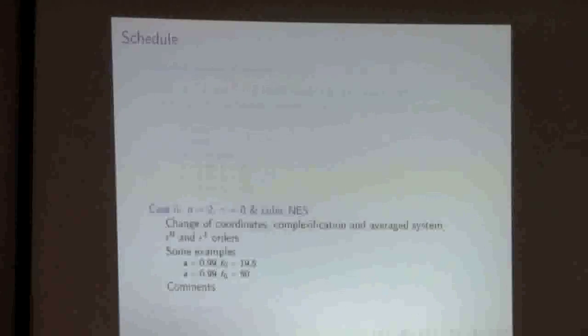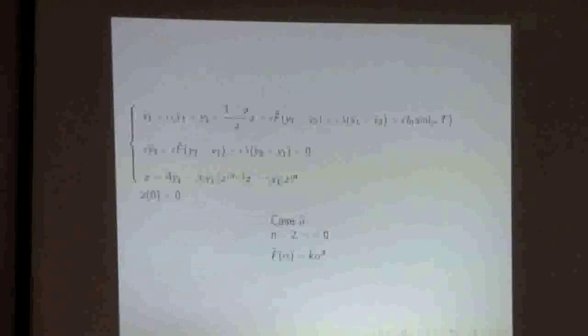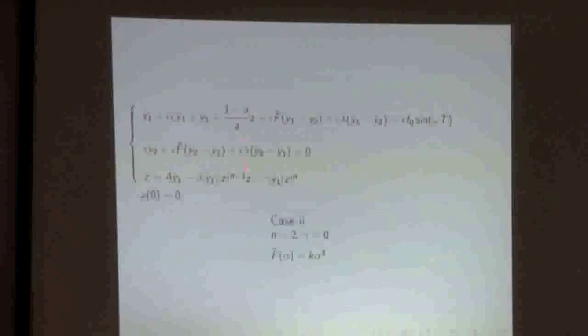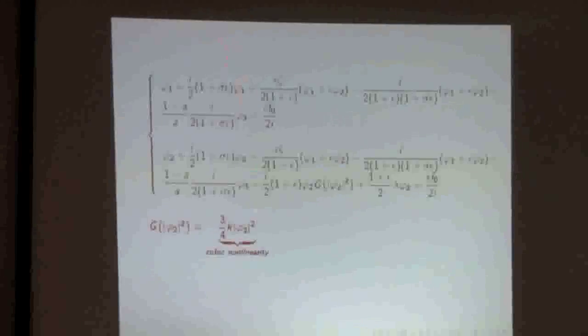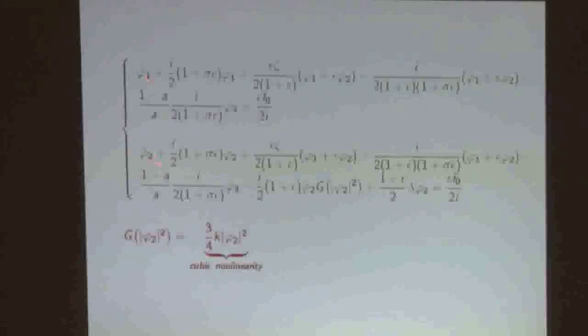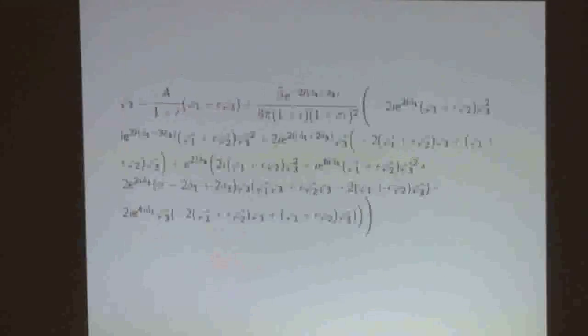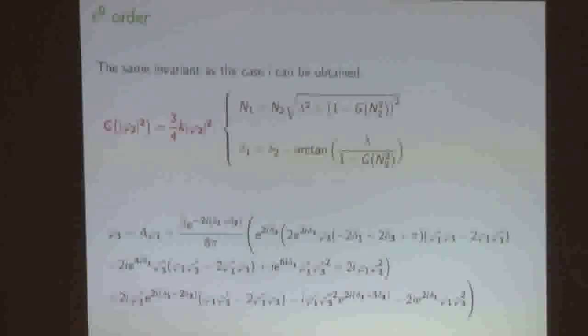Now let us consider the second case, n equal 2. So for n equal 2, I take the same Bouc-Wen model, but I consider now a cubic nonlinearity. So it is quite similar. You have again the phi1, phi2 equation by Manevich, completely similar. You have also an algebraic relation associated to the differential equation governing the internal variable, but it's only an algebraic equation.